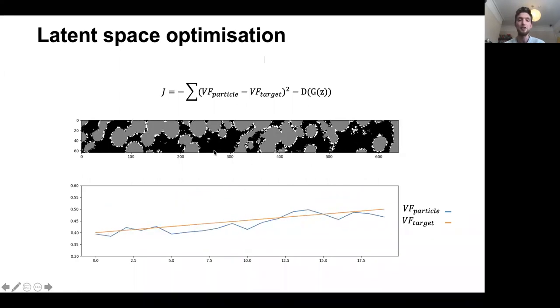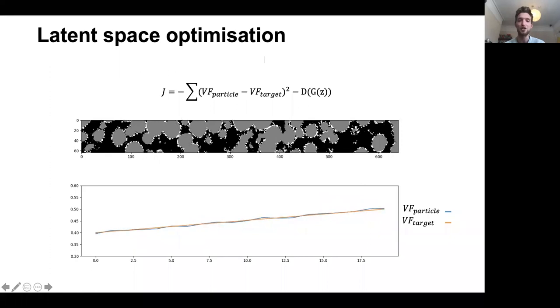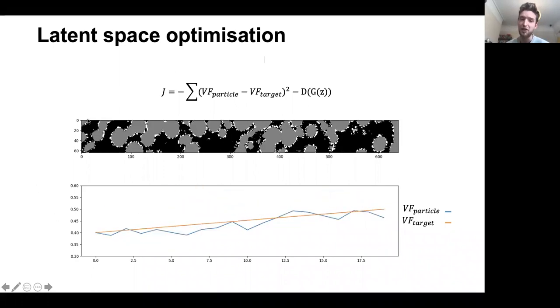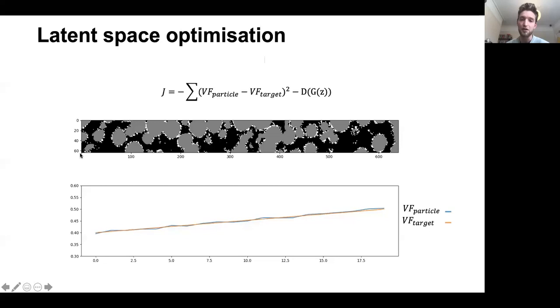And you can see that once we do that, the change is much smoother. Look at all these nice smooth circles, nice realistic looking NMC particles, and still a very, very good match for our target gradient. Just to be clear, this is actually a 3D volume. So we have 64 voxels down, 640 voxels across, and then there's also a depth of 64 voxels.